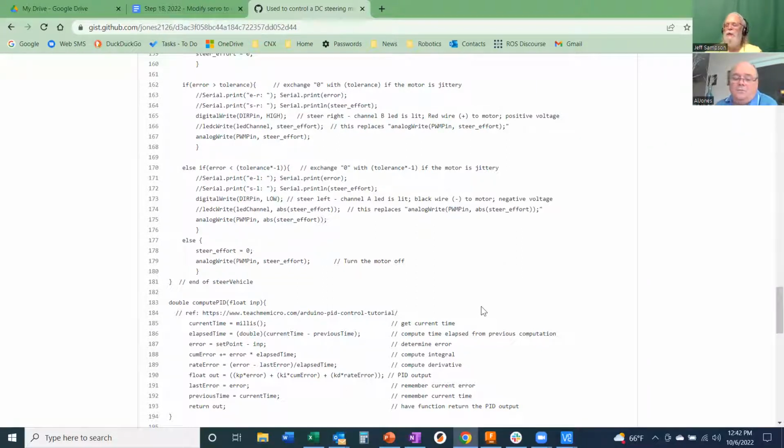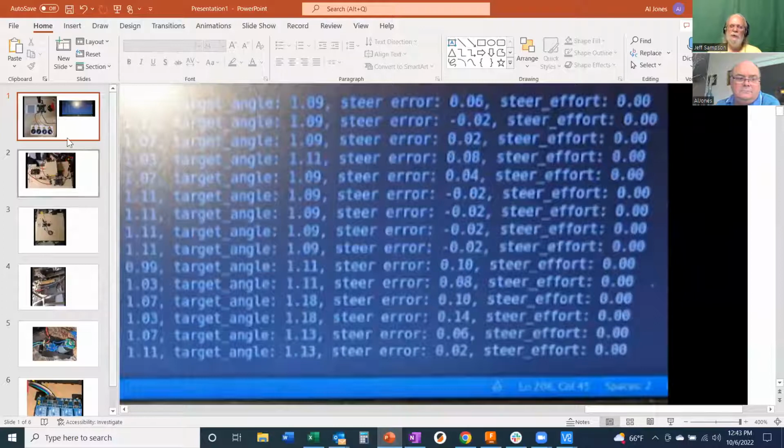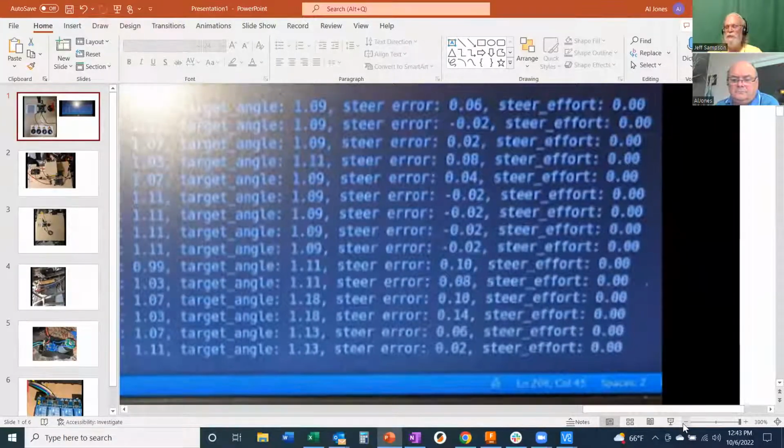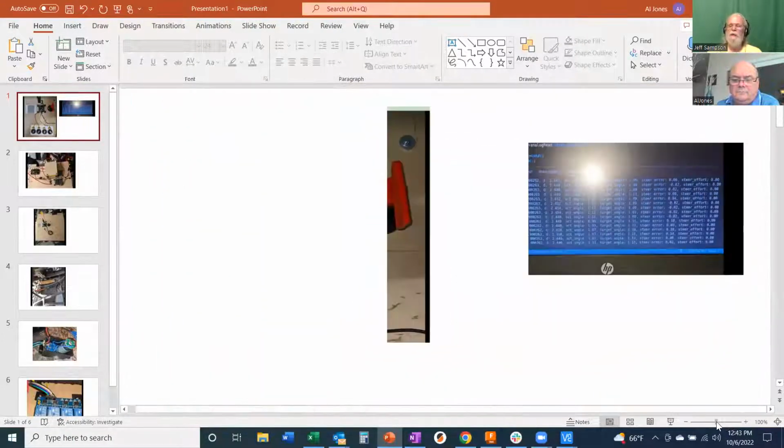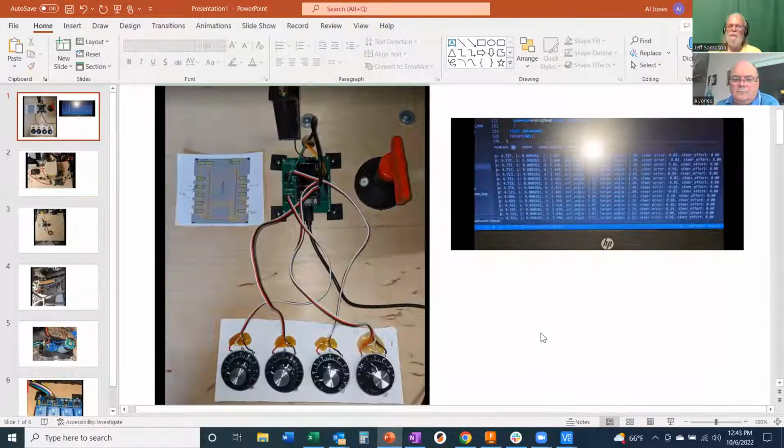Based on that, take this code and, where you read the target pot, put it out on the screen, and read the steering pot and put it on the screen, and with that running, plot that on the Arduino serial plotter or whatever, and see how noisy those are if you're not doing anything. It could be that once the motor starts up, the steering pot becomes more noisy because you've got longer wires on that. Anyway, that's where I think your jitter is going to come from, because you're reading your pots and you're not getting a stable DC value out of that.